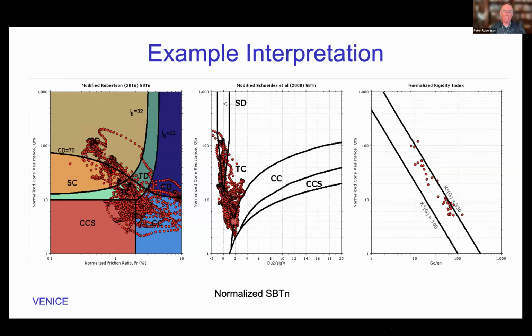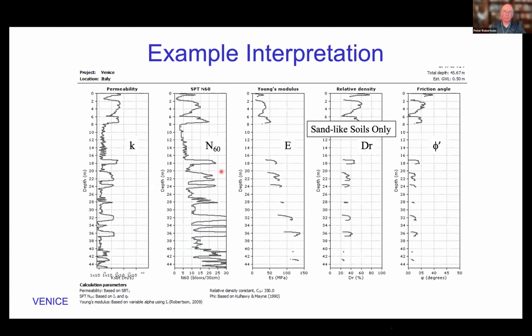The chart in the middle, the pore pressures are falling where you'd expect for a soil that has little or no microstructure. The boundary of microstructure was roughly here. The normally consolidated clay has a positive pore pressure, the over-consolidated silts have some negative pore pressure, and of course, the sands have either 0 or negative pore pressures.